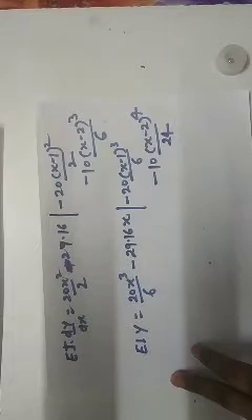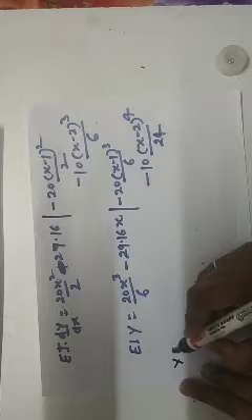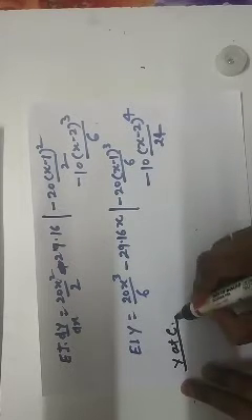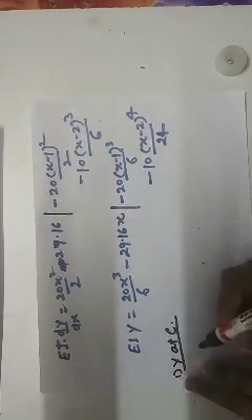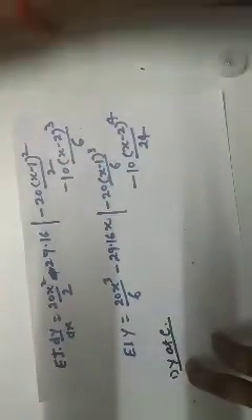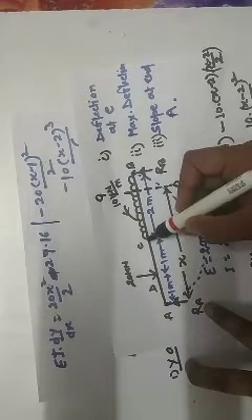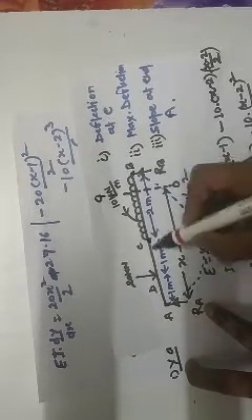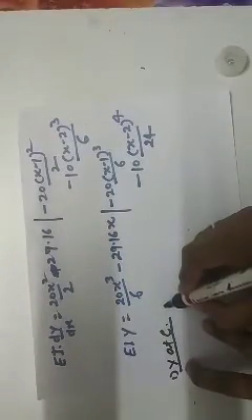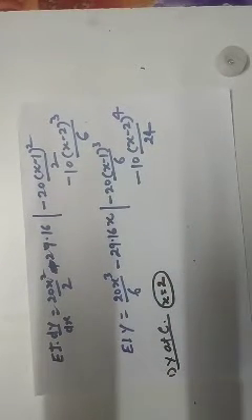Now what do we have to calculate? We have to calculate the deflection at C, that is y at C, the first point, right? So we know that for point C, in the beam loading diagram, x is equal to 2. We have to calculate the deflection at this point. So at this point, x is equal to 1 plus 1, 2, right? So for y at C, x is equal to 2. Put this value into the deflection equation.